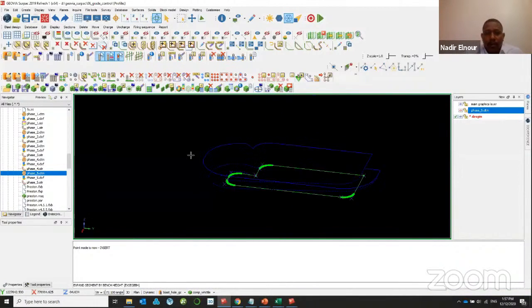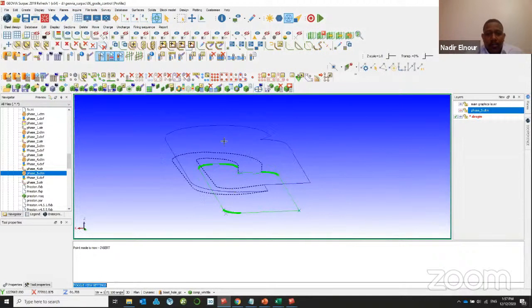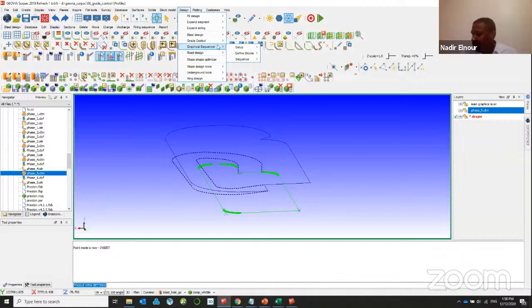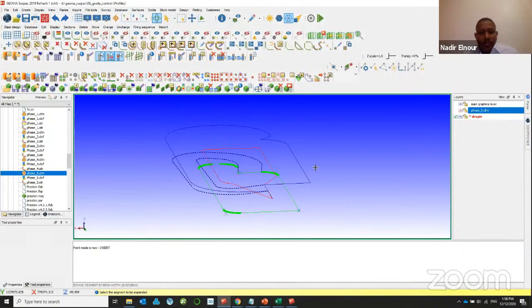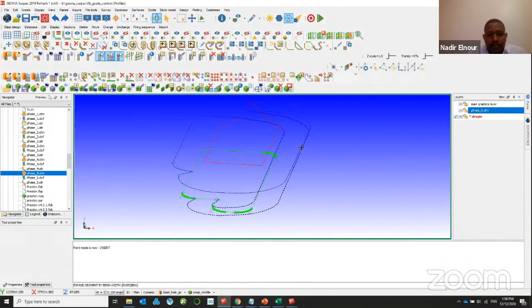But for now, our ramp also starts. If you can see the ramp here, the ramp also starts going up. So now we need to go and design our berm. I will design our berm and then I will show you how to permit. So now the berm is maybe 10 meters. If you need to add a switchback, you just click here. It will add a switchback for you. Then now you can see it has already added the switchback, the berm.